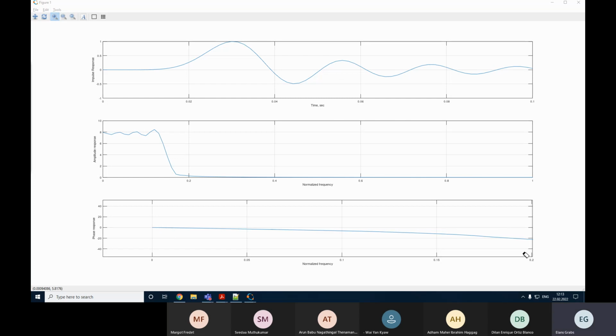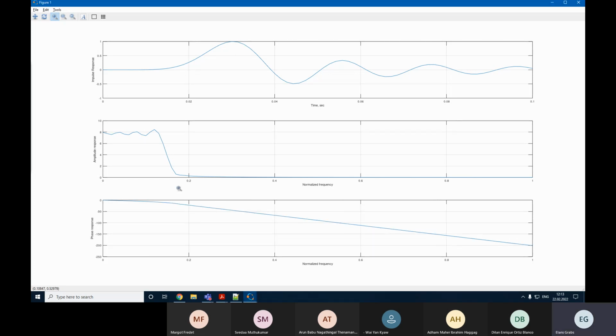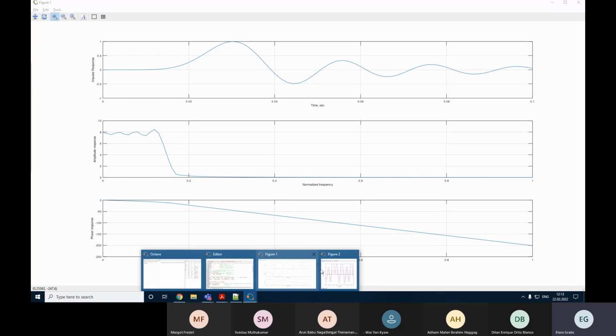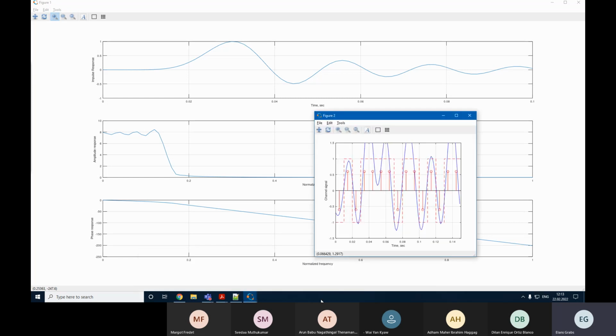Well, non-linearity. Yes, it's a convex line. So for that reason, the phase frequency response is no longer a linear function, and accordingly, group delay time is not a constant. So how did this mess up our signal? You can see it clearly here that in fact our signal has been distorted. Yes, distorted to some extent.